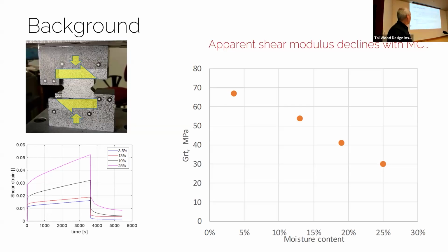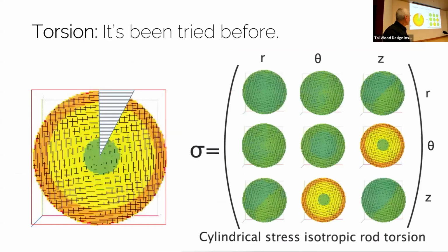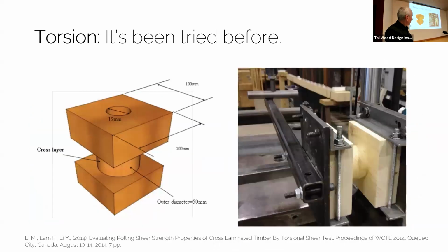So this is what motivates this thing. We would like to know more about it. Now, one of the ways of having shear isolated from other types of stress is in torsion. And it's like in circular shafts, isotropic shafts, this is a known thing. So here would be different components of stress being seen in the shafts. You see actually only this one being active in here.